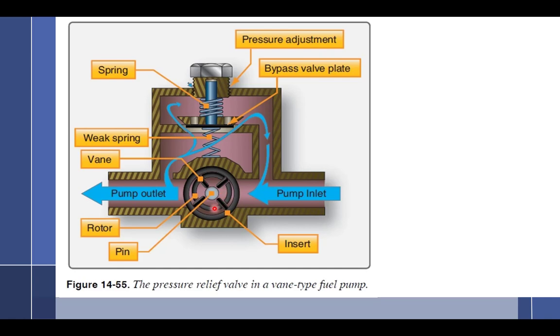If I turn this pump right here at 1 revolution per minute, it's going to put out a certain volume because every one of these little chambers has a certain volume. But if I turn it twice as fast, what's the volume going to be? Twice as much. So that'll be 2 revolutions per minute. It's constant displacement, meaning constant per revolution. So the higher the revolutions go, the more it's going to put out. All right, so we got that going.